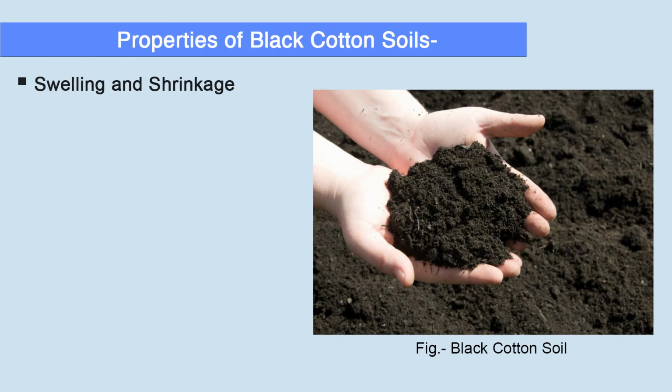This cyclic swelling and shrinkage can exert considerable forces on foundations, leading to structural damage. Therefore, designing foundations for structures on black cotton soils requires special considerations and techniques to mitigate these effects. Then what are the various properties of black cotton soil?